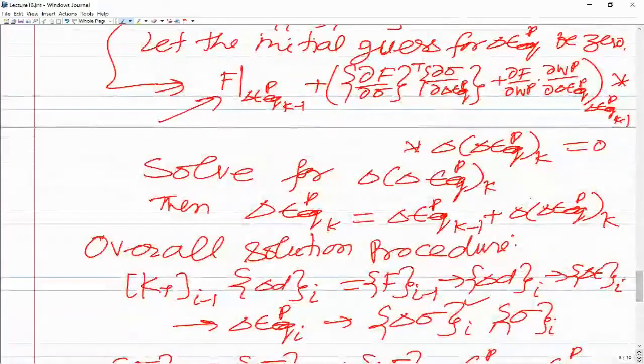The global iteration to get the converged delta d has the iteration variable I have set as i, and the local iteration, which is at each Gauss point of each element, has the iteration variable I have used, k. So there are two sets of iterations, global and local, involved here. This is how you will solve the problem.